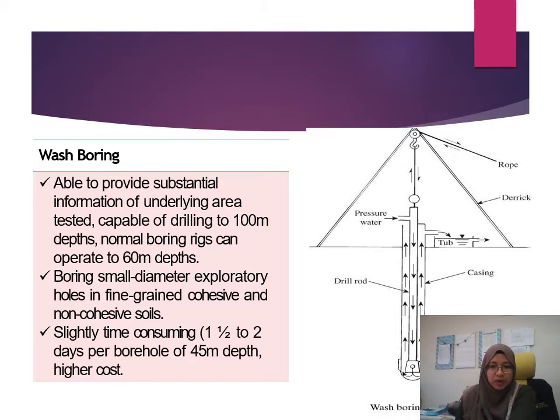So it is suitable for any type of soil, either cohesive or non-cohesive, but it is slightly time consuming. It requires 1.5 to 2 days per borehole of 40 meter depth, and the cost is very high. So the selection of the procedure of advancing borehole or site exploration depends on your cost. If your budget is very high and you require deeper soil data, you might go for wash boring, right?